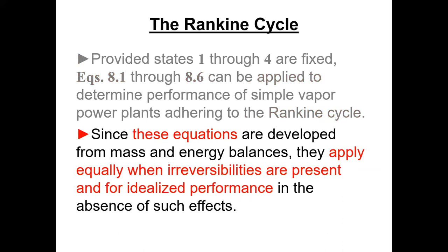This is an important note. Since these equations are developed from mass and energy balances, they apply equally when irreversibilities are present or for idealized performance. So we can still use those equations in either case. And we'll develop the assumptions around the ideal Rankine cycle here in just a minute. Then later on, we'll probably work some problems that have actual state points that would include irreversibilities in them. But those basic equations hold in either case.